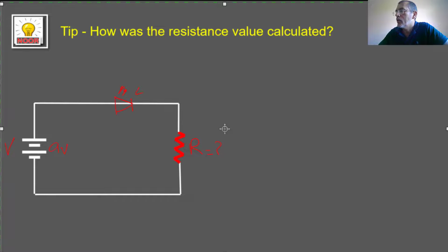So this is our LED here. Remember, we mentioned there is a 1.7 volt drop here. Current flows from the positive side, as I mentioned. So there is some current I, and it shouldn't be more than 20 milliampere.